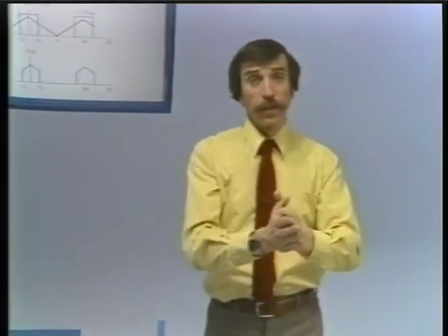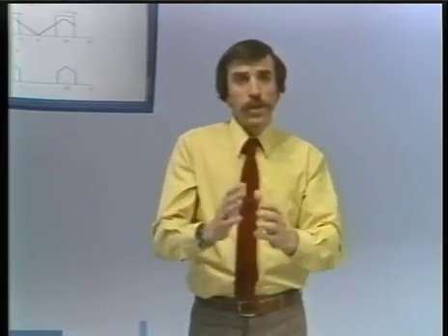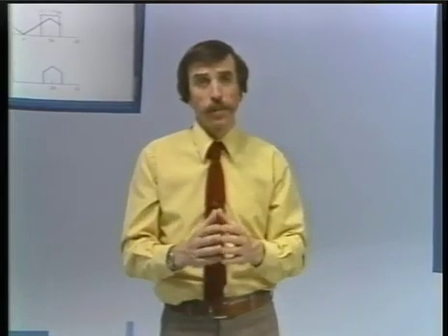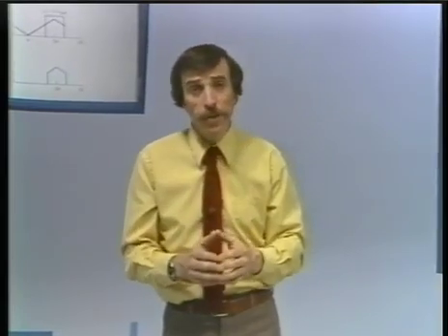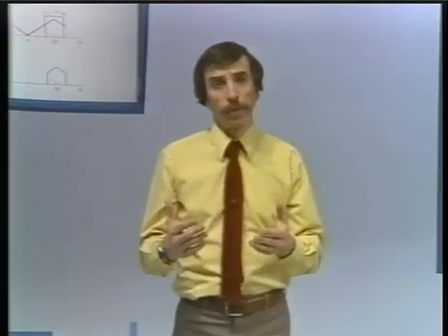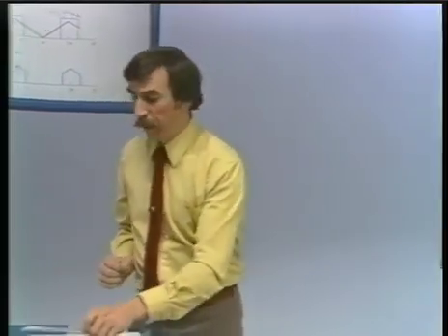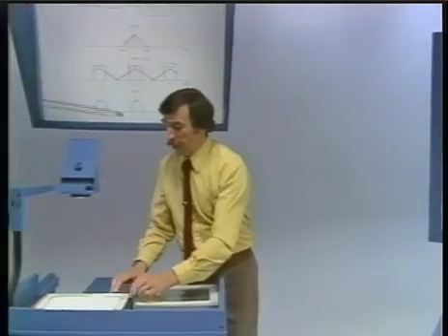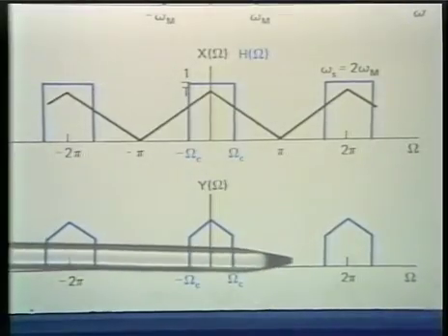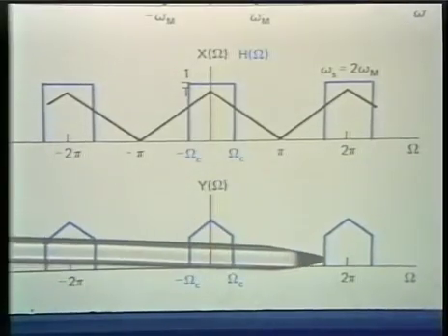In other words, sampling it, which would be more or less associated with a different sampling rate for the continuous time signals involved. So I could now go through a process which is commonly referred to as downsampling, that is, lowering the sampling rate. When we do that, of course, what's going to happen is that this spectral energy will now fill out more of the band.